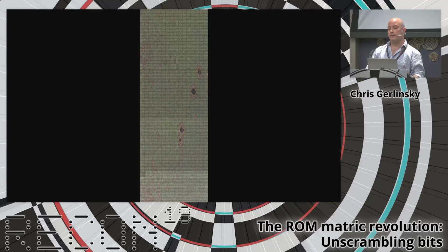If I need full ROM extraction, I can repeat it on 2 different chips. Those holes are probably going to end up in different spots. That works quite well. Or another option is to get into polishing a chip instead of using the wet etching.